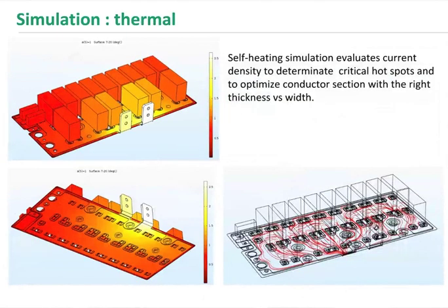Of course, next to the traditional inductance, there are also possibilities to make thermal simulations. Here is a good example, again on the same model, where we run the heat simulation and put 300 amps through the busbar and through these sub-assemblies. It may be a little bit misleading, but if you look, the higher temperature is actually at the terminals level, the ones that are white, and you can see from the top and from the bottom.